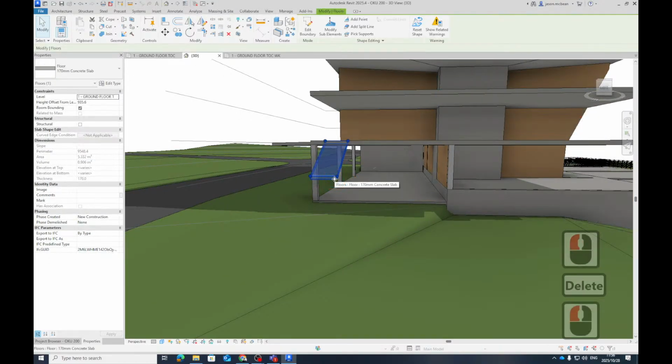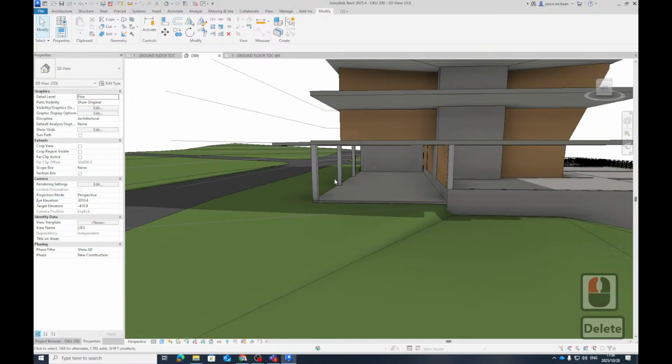When I open the basement and then the ground floor, I can see the basement. That's very quick. You've just enabled your underlay. Just say none. You enable it to see where things are below.